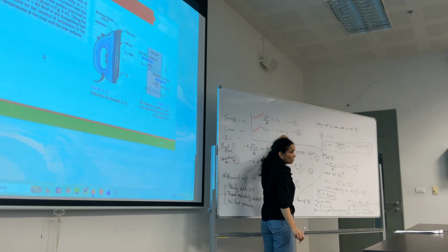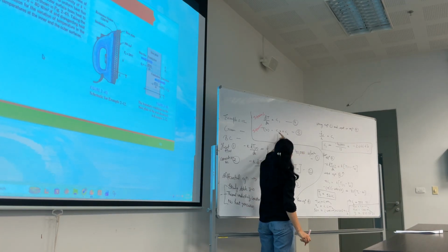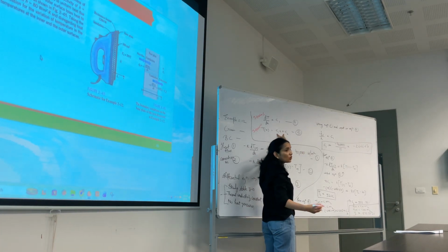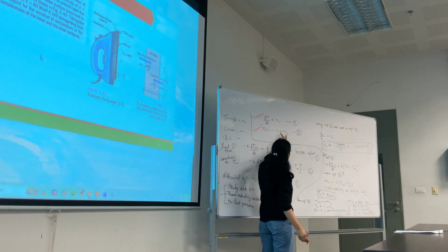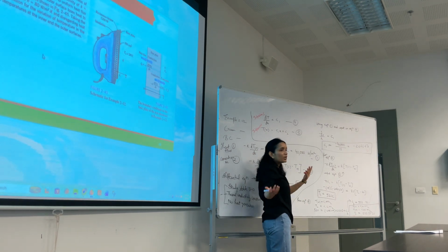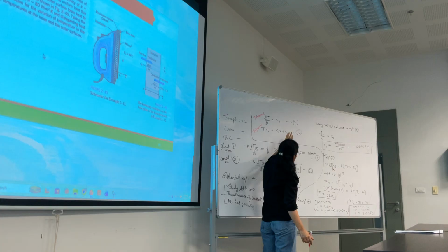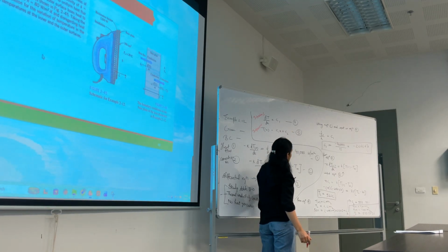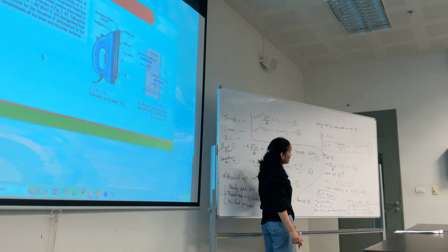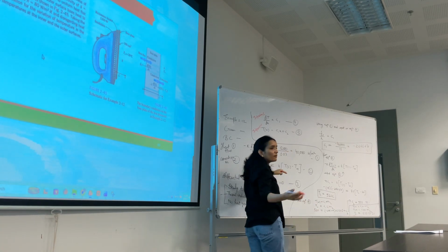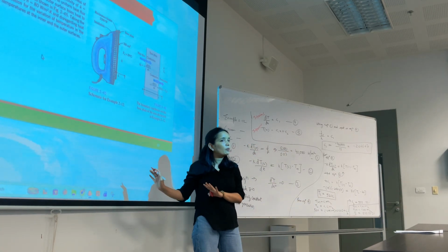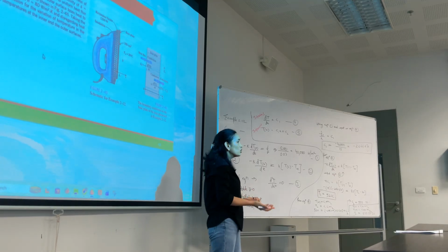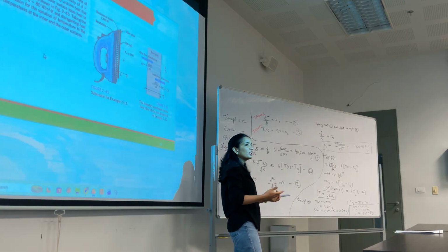Now you have this equation which you will always get when you are solving this, but we need the value of C1 and C2. The value of C1 and C2 is going to be different for every equation. In order to find the value of C1 and C2, we use the boundary conditions. These boundary conditions will be different for every case, even if it's a plane wall. The value of thermal conductivity and convection are going to be different.